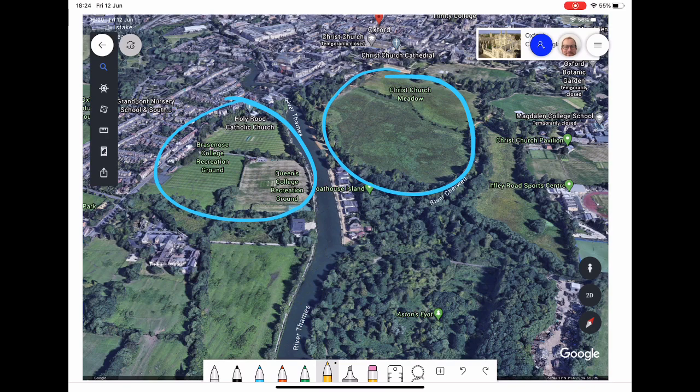An example of soft engineering that is happening right on our doorstep just up in Oxford, I've circled two areas, and we've got here a meadow next to the River Thames, and we've also got some sports pitches. The reason that they've been put there is something called flood plain zoning. That means essentially there are restrictions put on what you can actually build on certain bits of the floodplain, and they leave these areas because they're relatively low cost in terms of if they flood, it doesn't matter. Their value is not that high, and so they act as natural barriers.